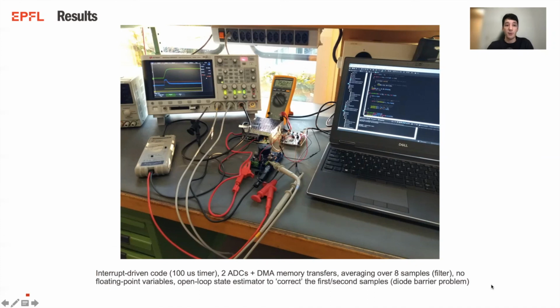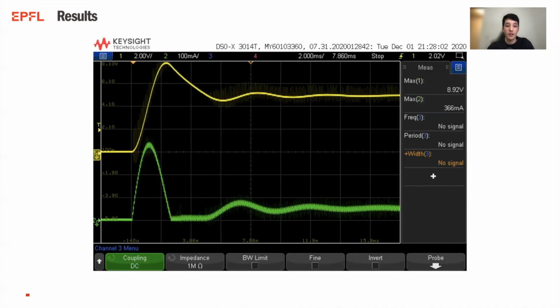Now let's talk results. What you see on your screen is the open loop response of this dynamical system. It looks pretty bad. Even though you want to settle down at 5 volts, the voltage waveform peaks at 8. The current is even worse. Look at the size of this hill when compared to the final steady state value. That's an overshoot of over 700%.